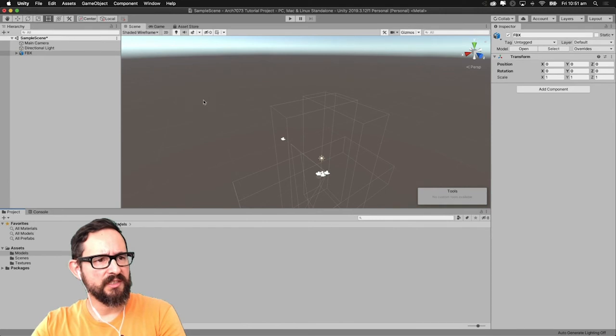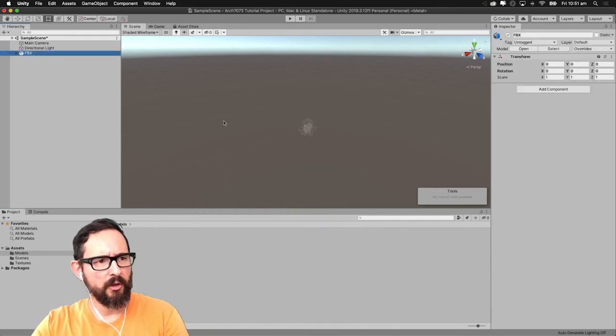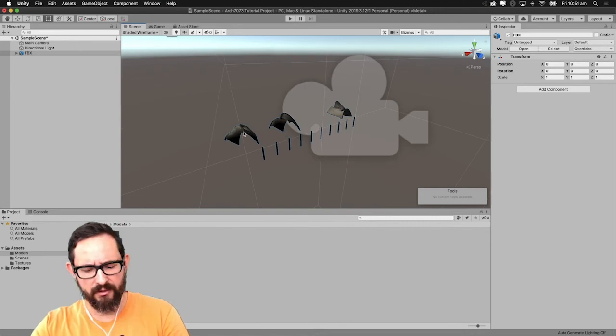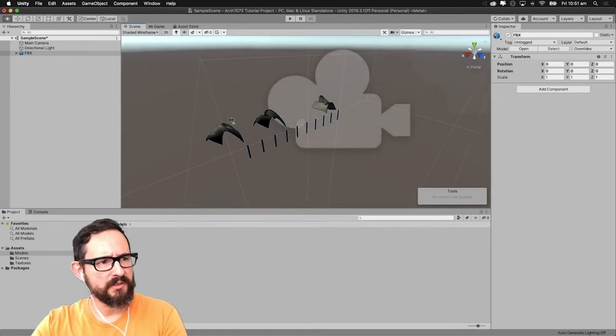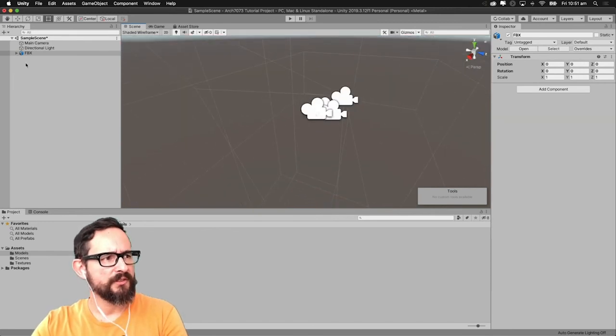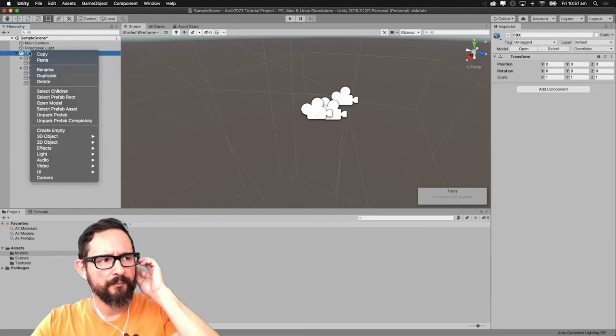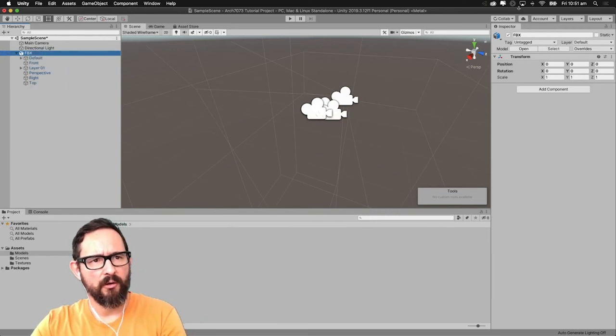Right? Once it's in the sample scene, you start seeing it. It will pop up into the model. In order to zoom into the model, press F. F is to zoom in to the selected elements, and so you start seeing, okay, so that's my model. Obviously it's extremely small, so the first thing we need to see, before we open whatever is inside of it, again, there's a hierarchy, but if you select the top or the name, you can rename it as well. If you right click, you can rename everything. The same thing can be done on the right hand side.